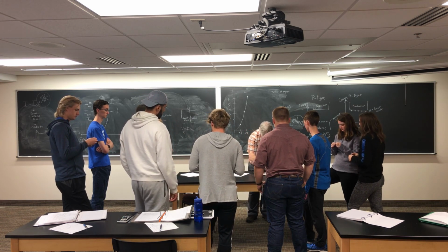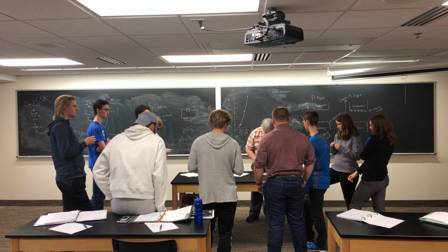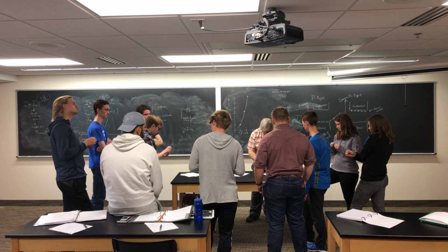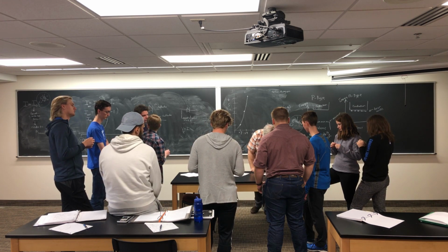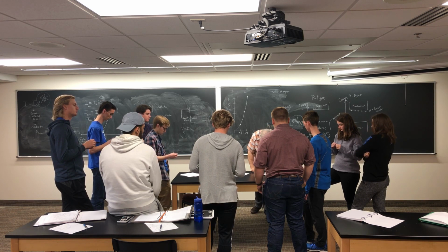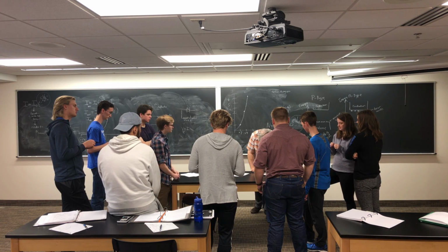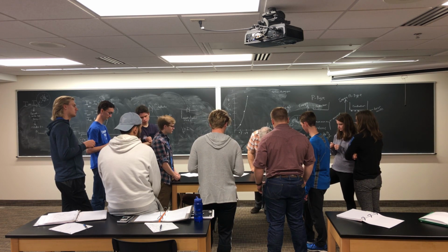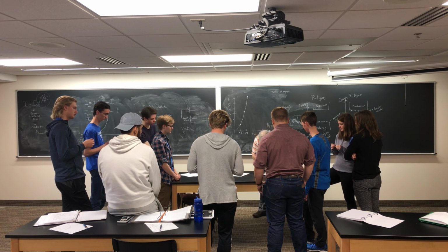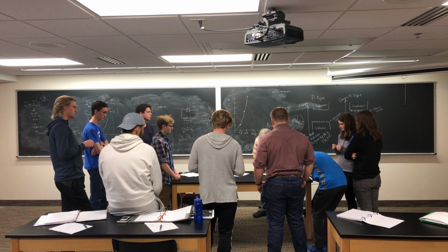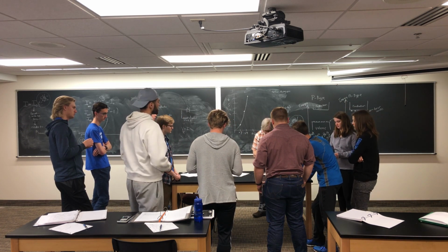Again, if I reverse the current, I should get nothing out of this, but this is forward biasing it again. And I start to get, it looks like no flow of current through there until I reach a certain voltage. About 0.6, you probably can't see it. I'm starting to see a little, as I go on up, I can see it. You can see it glowing pretty good there.